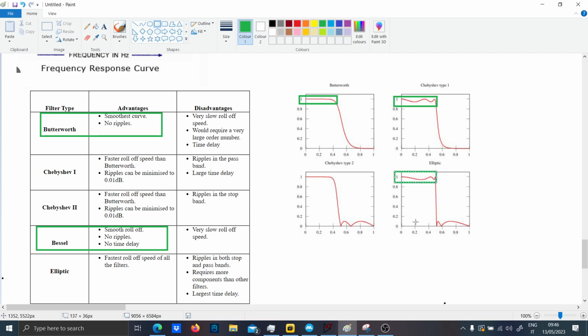It means basically that whenever you're going to read your signal here, if you use this kind of filters for measurement, it's going to be a problem if the passband ripple is too high, because if you have, for instance, 1 kHz of a signal with some ripple, noise at megahertz, the signal at 1 kHz can be either attenuated or amplified a bit. And if you want a precise measurement, you honestly don't want that.